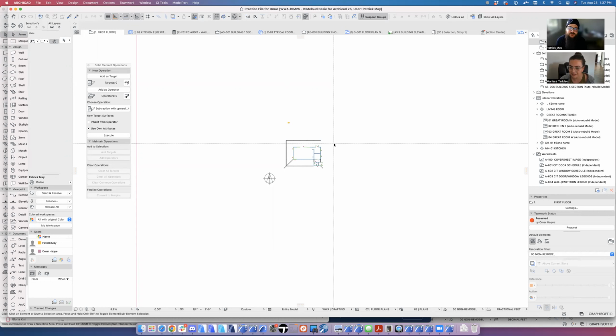And maybe it's slower, maybe it's not. Honestly, there are a lot of things in ArchiCAD where I know Rena, for example, wants to be able to place the thing exactly where she wants right away. And so she has all these tricks: when this beam needs to be 2 feet off the corner of the wall, she makes that happen and places it right where it needs to go. Whereas I'm a big fan of dropping the beam in and then moving it to the corner and over 2 feet.